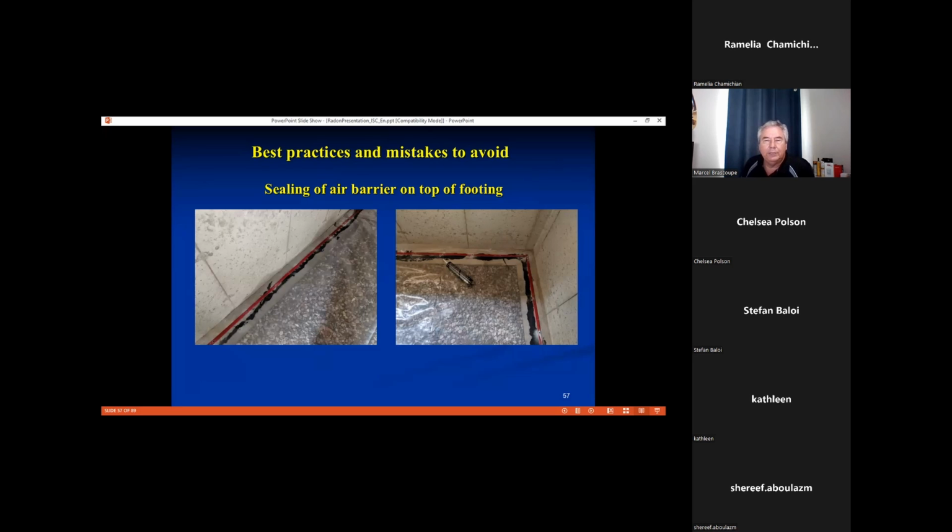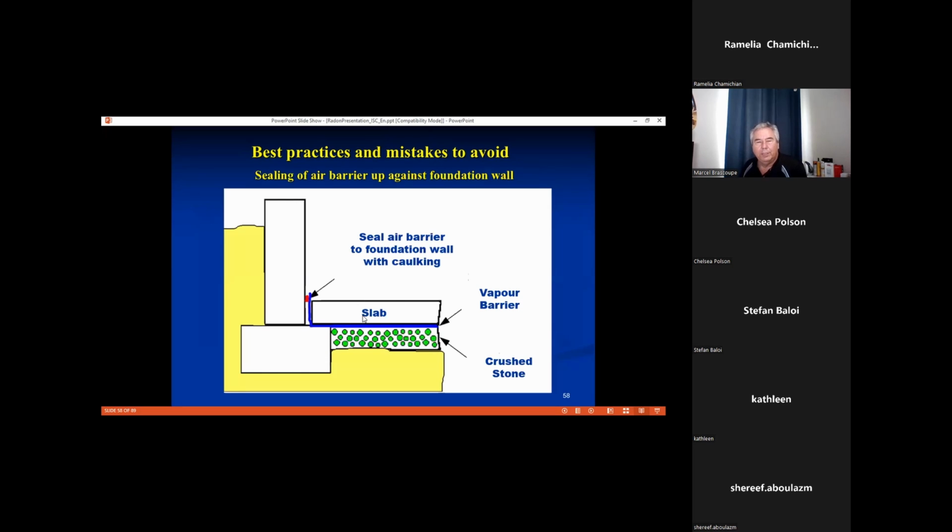And in certain cases, if you have an ICF home with styrofoam forms, that may be your only option. There's not too many products that actually stick to the foam itself. Most caulkings will eat it away. So here, like we were saying, the option is coming up with your plastic vapor barrier and actually sealing